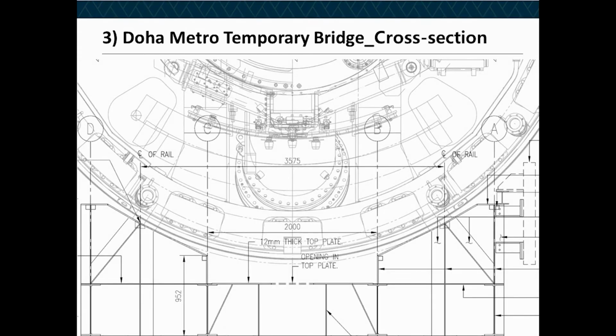This is the cross section. So here you have the bottom line of the tunnel boring machine, and in the bottom here you have where they wanted the MSV to be able to drive afterwards. And so that line there was our top profile. They then welded 50mm rails on here for this tunnel boring machine. The boring machine itself is not actually that big. It's only about 7 meters in diameter, which is, by tunnel boring machine standards, fairly mid-range, I think.